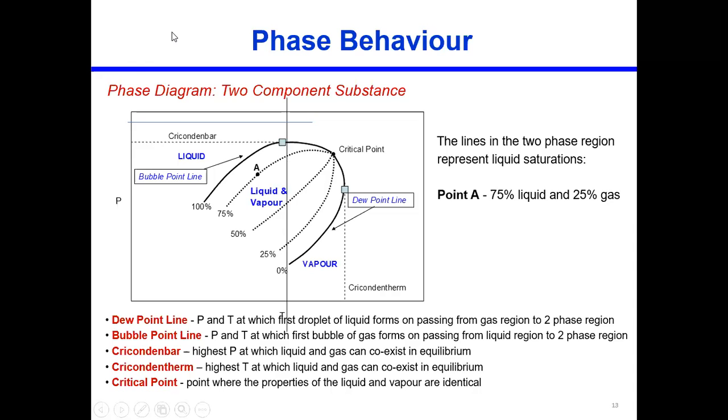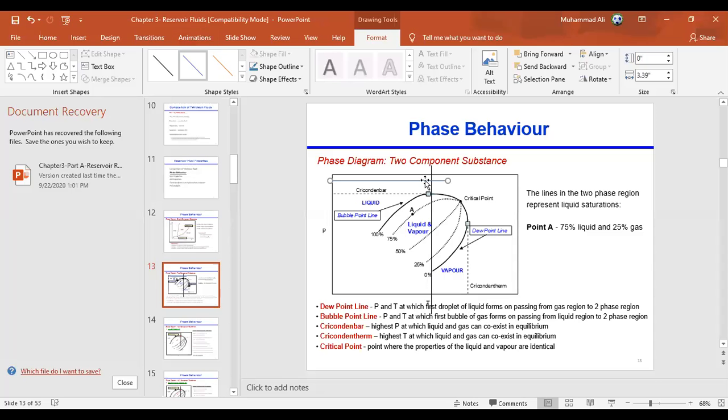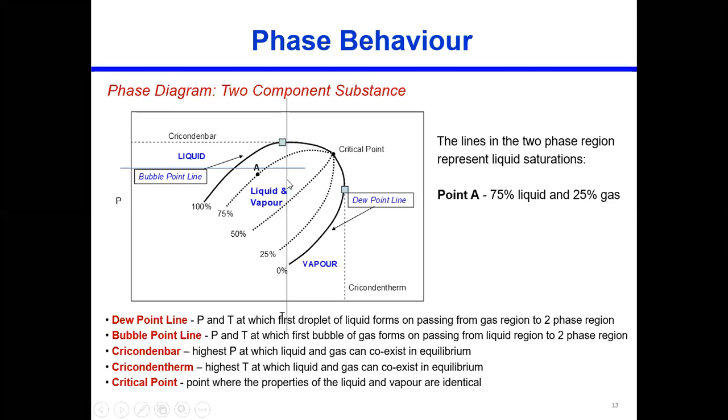So when the pressure declines, in this case here is single phase undersaturated condition. But when the pressure declines, this can come in a zone. Now maybe here we have a different situation. Here we don't have a single phase. Here probably we have oil, which is around, you can say, 60%, and 40% probably represents the gas at this point. There's a critical point also. So these lines, X and Y, the pressure line and the temperature line, exactly tell us what is the current pressure and what is the current temperature of the reservoir. This is the first thing.